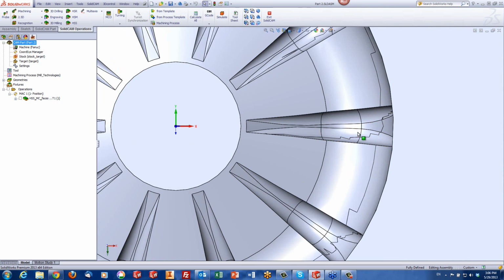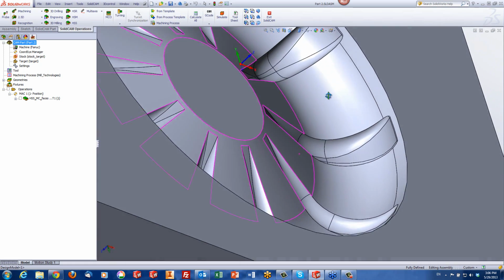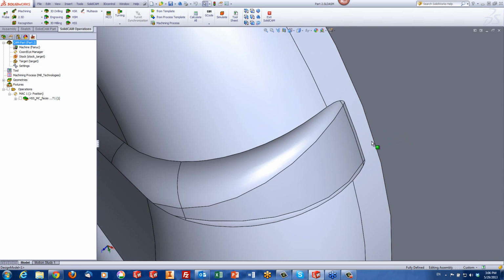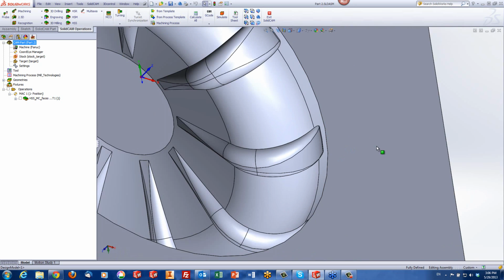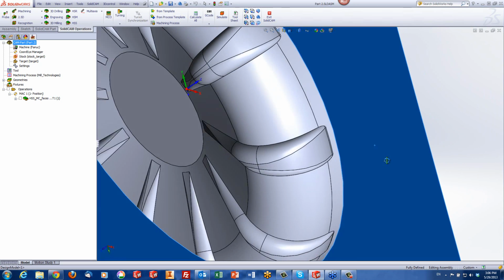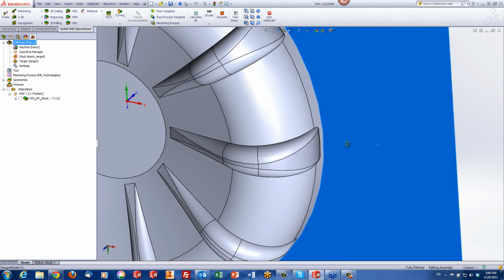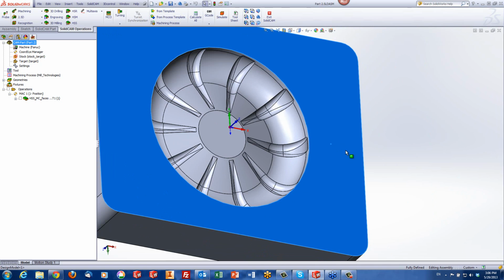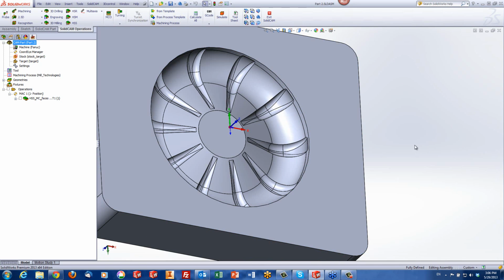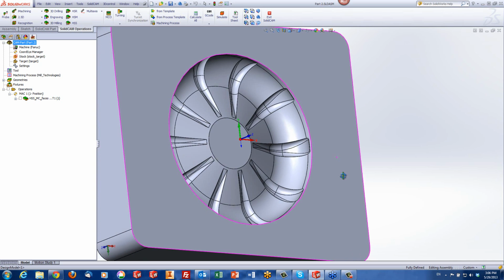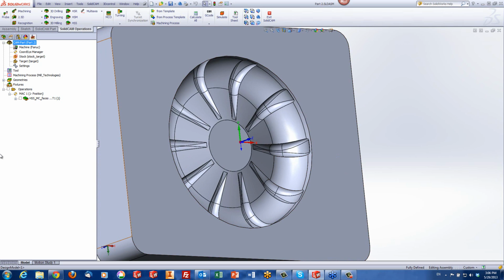Now, it looks like a pretty simple task to do. However, it should be noted that this surface is actually an undercut underneath this top surface over here. It actually goes underneath it. So the only way to do it is using HSS. Now, the type of tool obviously has to be the correct tool type. And in this particular case, the only way to get in there properly is using what we call a Lollipop tool. Okay, now, let me just open up the operation.